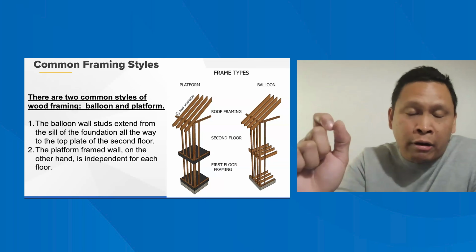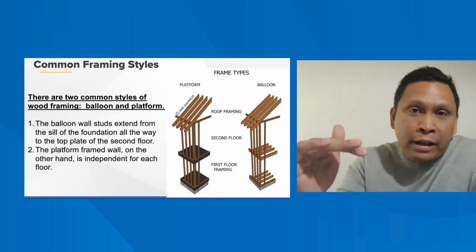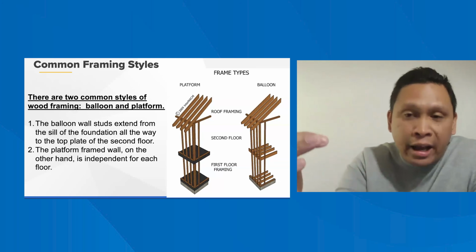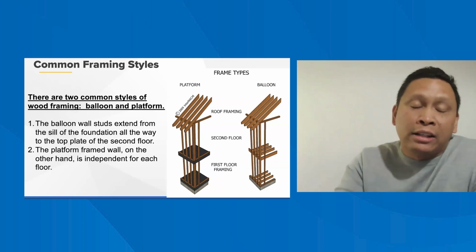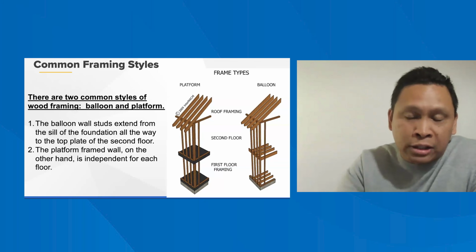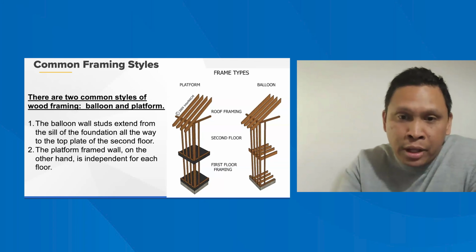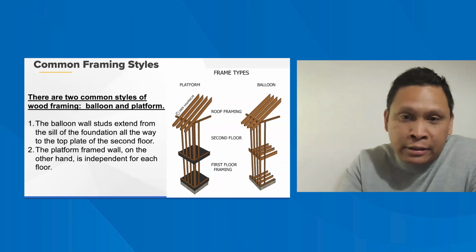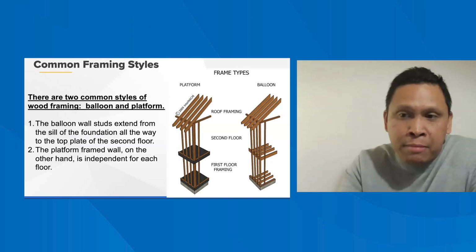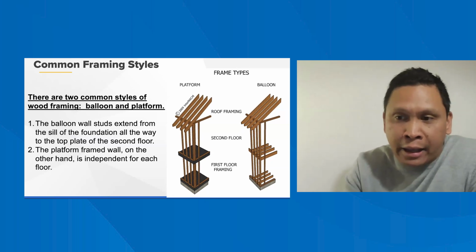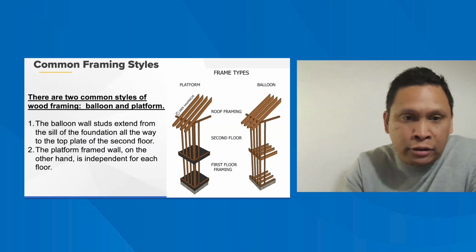What they're doing is, any hole that's transferring from one floor to the next floor, they're spraying it with this spray foam to try to seal off the opening as much as possible to slow the spread of fire. Balloon framing is really interesting, but it can be mitigated by adding fire stops.